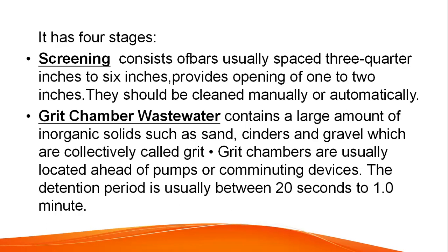Grit chamber. Wastewater contains a large amount of inorganic solids such as sand, cinders, and gravel, which are collectively called grit. Grit chambers are usually located ahead of pumps or comminuting devices. The detention period is usually between 20 seconds and 1.0 minute.